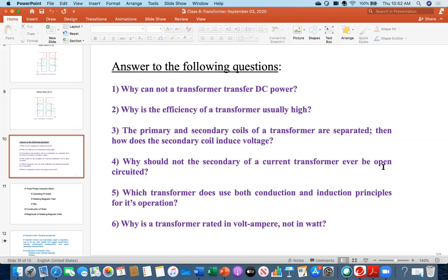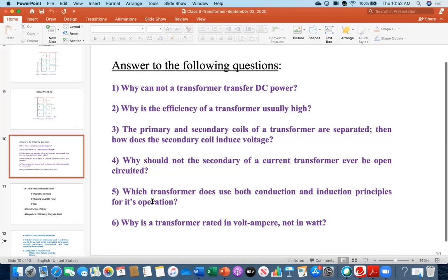So you remember I was discussing, if you need to take out the ammeter from the secondary side, before taking out the ammeter, please connect the short circuiting switch. You remember I was showing the short circuiting switch. So first close that short circuiting switch and then take out the ammeter, so that the secondary is never ever open circuited. So you write it in whatever best way you can, but those are the technical points that should lie in your answer. Okay.